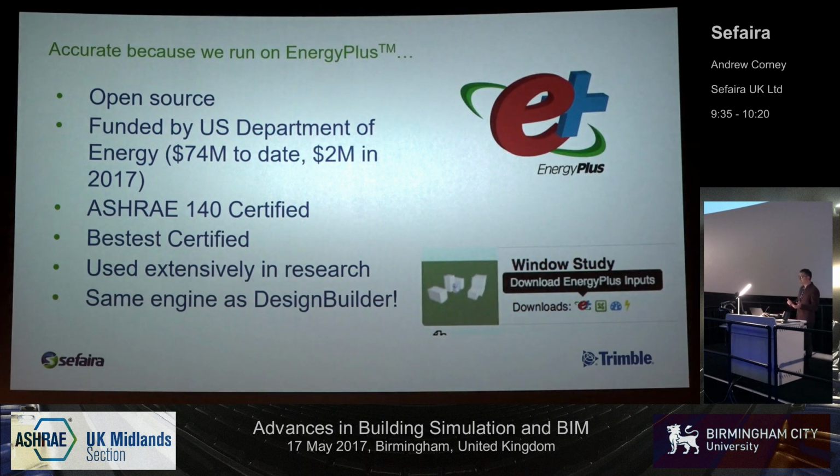Why is Sefaira accurate? Well, we run in the cloud, we run on EnergyPlus. For those of you who don't know what EnergyPlus is, it's an open source building physics engine funded by the US Department of Energy. It's had over $74 million worth of US government funding to date. You can decide how valuable that's been, but they're still investing $2 million this year. It's ASHRAE 140 certified, BESTEST certified, used extensively in research, and also by DesignBuilder, which is one of the other software tools you'll hear about today, and many other building physics software tools.